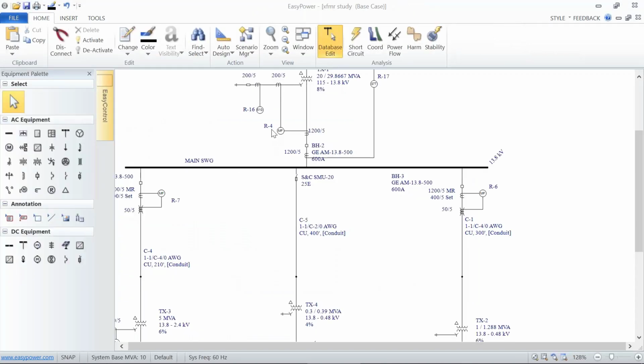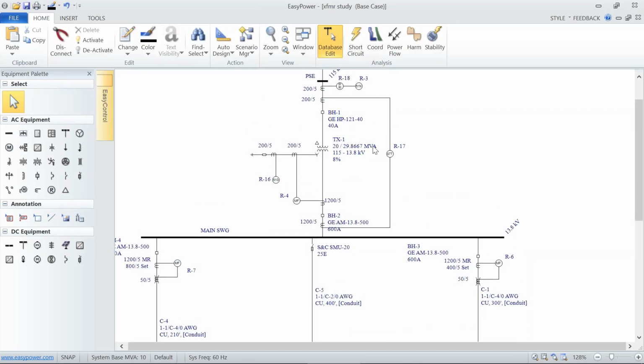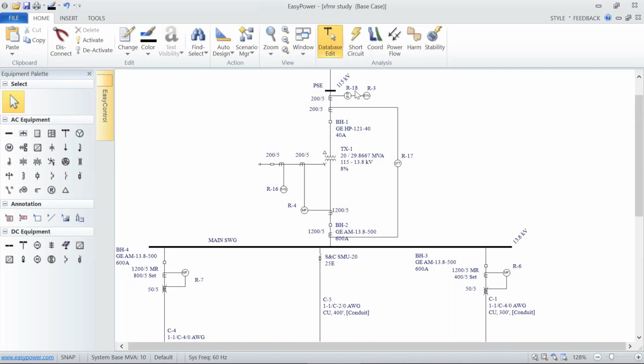Now, when we move on to the phase over current relay that's being used in the secondary side, we have a couple gears to shift. One is we're looking at a zone of protection for this relay to be different than from either the phase over current for the primary side or the differential. And it also emphasizes the fact that we have overlapping zones.